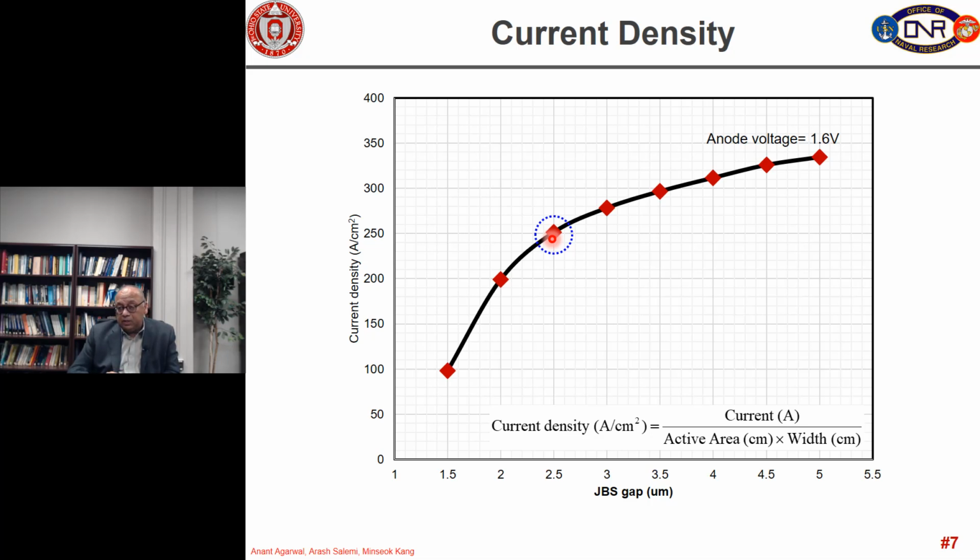So, from this current density, now we can design a cell size and the full chip for a given current. So, if you want, for example, 25 amp device, then we can use the current density of 250 amps per centimeter square, calculate the area, and then repeat this cell in 2 dimensions in x and y direction, which we will show you later in the next lecture, and create our footprint of the device.